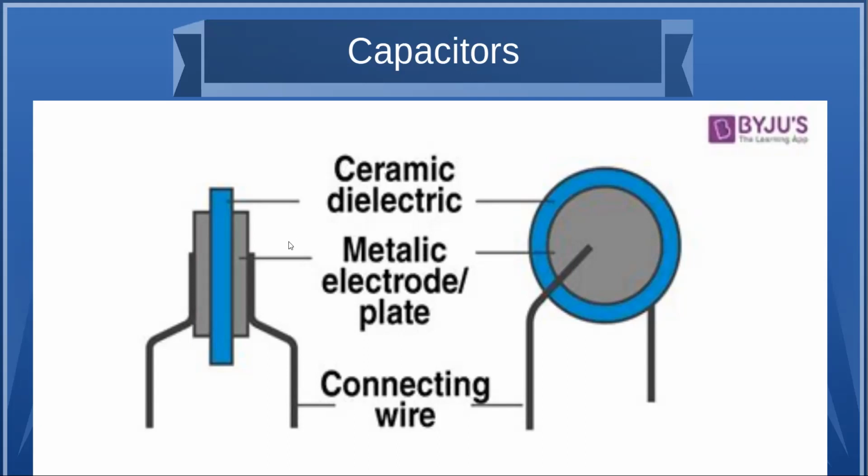This is a typical ceramic capacitor where it's got a thin piece of ceramic and they plate some sort of metal on there and make the contacts and then coat it with usually another kind of ceramic to insulate it. It's probably the most common capacitor you'll see. It covers all the smaller values and they're cheap. Obviously, it doesn't take much to make them.